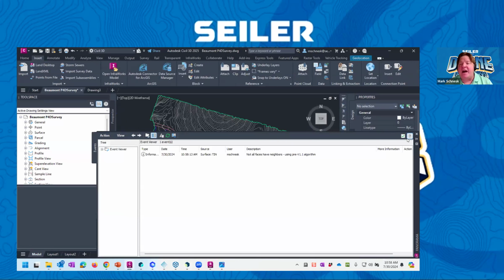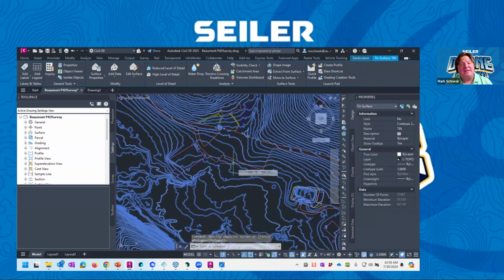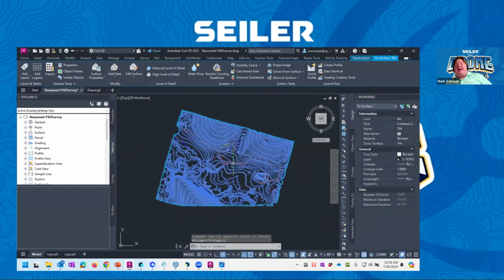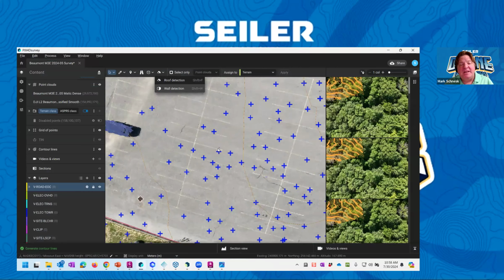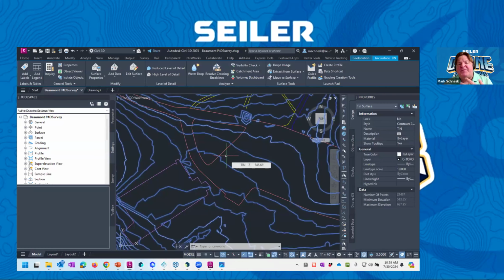I can use that contour that's there, or I can turn on the CAD contours. But any of the surface that I just exported is there as this full Civil 3D surface. I can bring in the COGO points from those features here. All these plus signs are the feature extracted grid of points. I can bring those in as COGO points in the end to create my Civil 3D object. So it's fairly straightforward. You're just using the point cloud data as the basis.